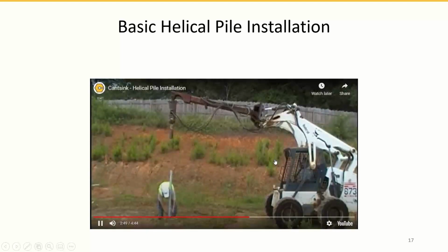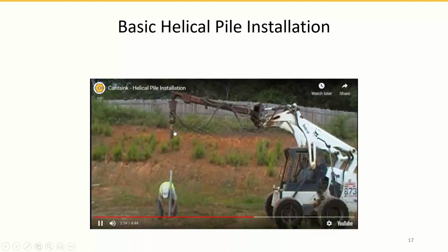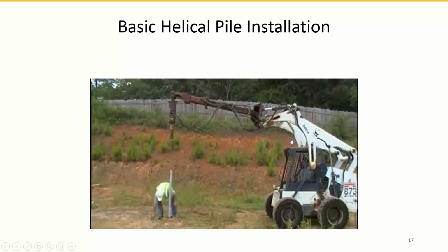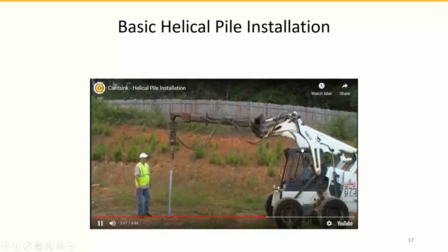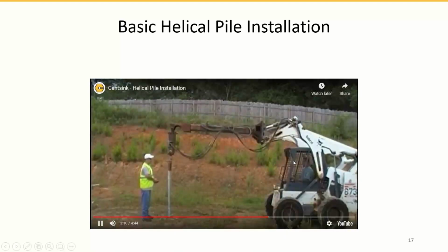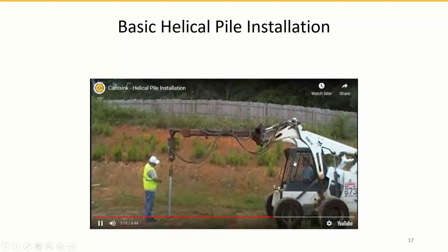This is just for showing it, and I'm going to tell them we have to do another video to show you where the torque indicator should be. That's a very good question. Thank you very much. Sometimes we do some helical piles around the place, and this is not a real project. He has a pressure gauge in front of him right here, and he's reading it. But this is just for showing you how the helical pile is installed. Thanks for asking. We don't have the torque indicator there, but it has to be there for real projects.